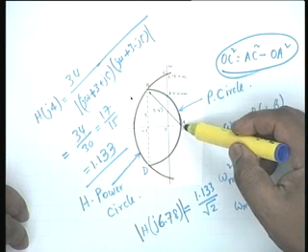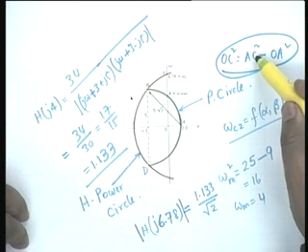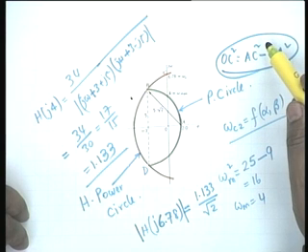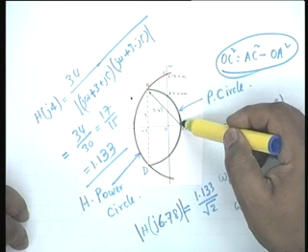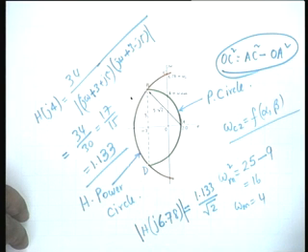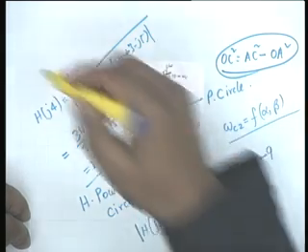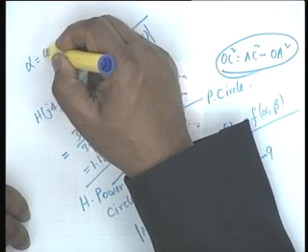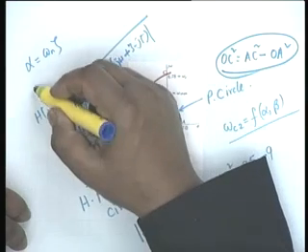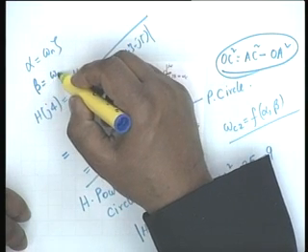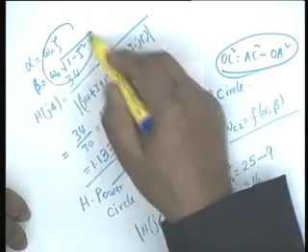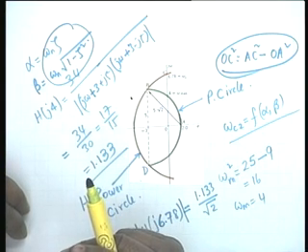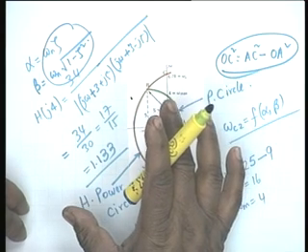You see, OC squared is AC squared, which is obviously 2 beta squared, and OA squared is beta minus alpha whole squared, and therefore you can find out in terms of beta and alpha and substitute alpha as equal to omega n times zeta and beta as equal to omega n times square root of 1 minus zeta square to obtain the expression in terms of omega n and zeta. It may be helpful to have this expression also ready.